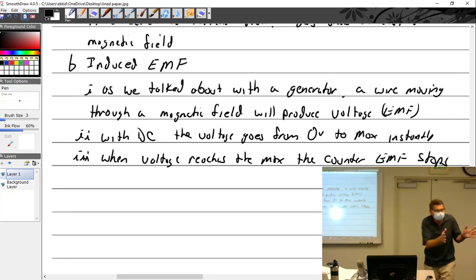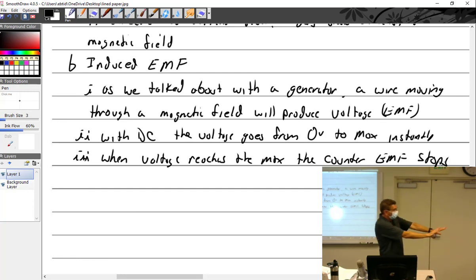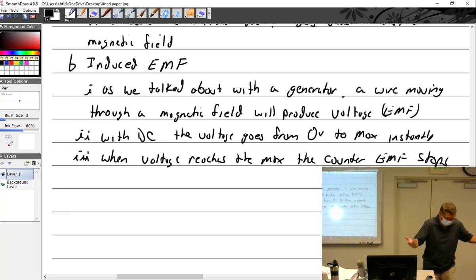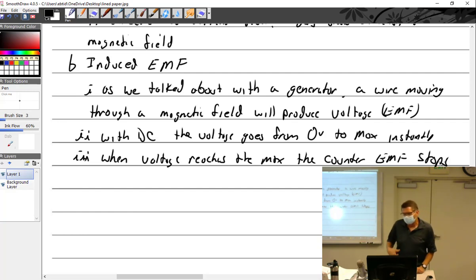Now, the funny thing about AC is that it's always going back and forth. The electrons are coming from that way, hit a coil, and it goes, whoa, everybody stop. Then it slowly builds up and peaks out, and then it goes the other way. So now everybody stop this way. It's constantly pushing back whichever way the electrons want to go. What does that sound like? Trying to resist? Creating its own resistance? It's creating its own resistance. But take an ohm meter and put it across it. What are you going to get? That's fine, doesn't it? Throw it in an AC circuit, and now you've got this resistance that has been built up in it, but only in an AC circuit. We'll get more into that in a minute.